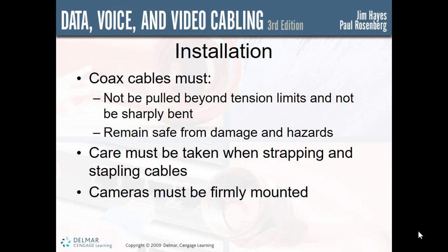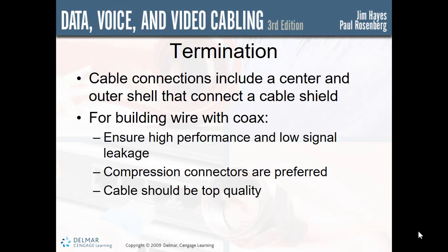Now, as we talked about earlier, security cameras must be firmly mounted. In addition to standard wall mounting brackets, cameras may also be mounted in vandal-resisting cases, which are recommended in trouble-prone areas. Mountings are also available with built-in panning and tilting mechanisms. Obviously, these will cost a bit more than the standard mounting, but will provide an additional benefit. However, they cannot be used in all installations, particularly not with video motion detector devices.